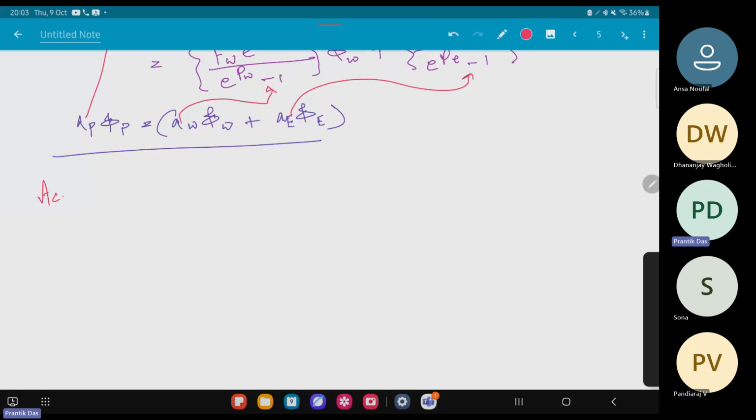And going to the accuracy, this accuracy is exact for 1D. Typically you don't have any accuracy problems since you are using the exact solution for the discretization. But this is one of the schemes we don't use. One fundamental reason is that it is expensive to calculate the exponentials. This exponential of PW is expensive to calculate. So then this becomes an issue.